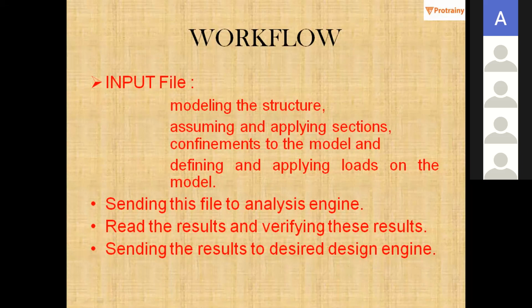After doing this, of course, you need to provide some constraints. There must be some constraints to your structure, so you need to apply these constraints and confinements to your model. At last comes the loading part, where you define the loads and then apply the loads to this model.